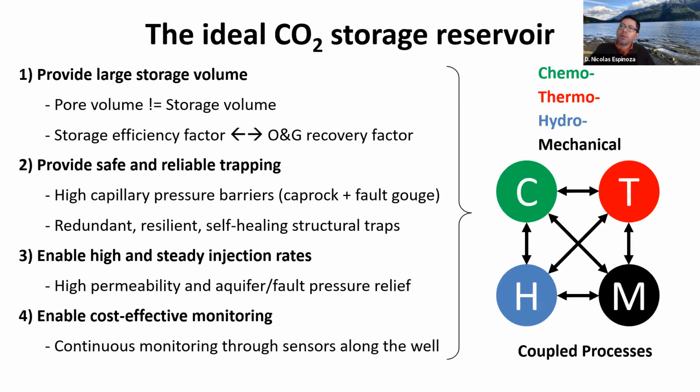So when we put mechanics into the picture, we see that some of the objectives of an ideal CO2 storage reservoir, as I was telling you before, are going to have some conflict with geomechanics. For example, we cannot assume that the entire pore volume is going to be equal to the storage volume because we really have to push, for example, brine to make space for CO2.